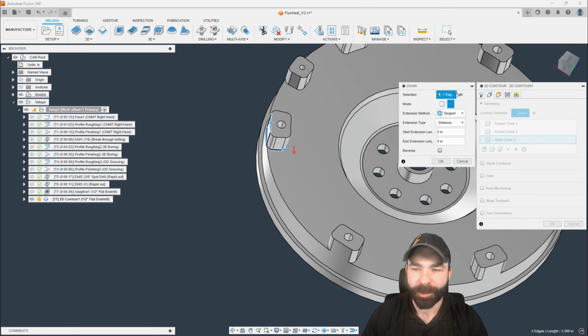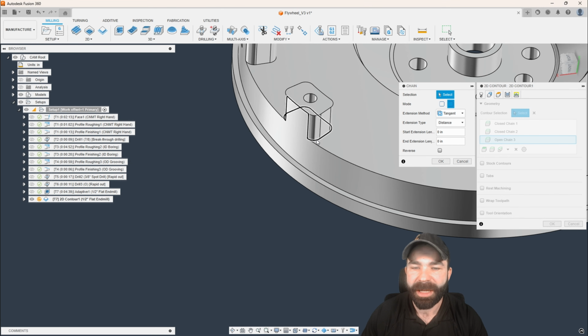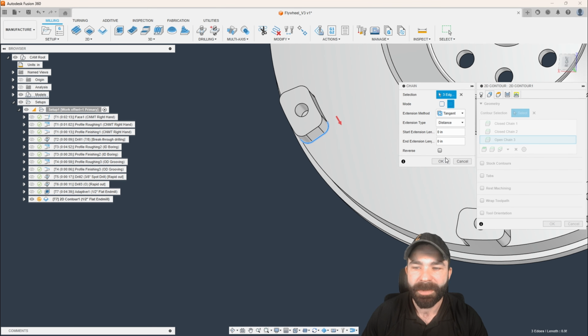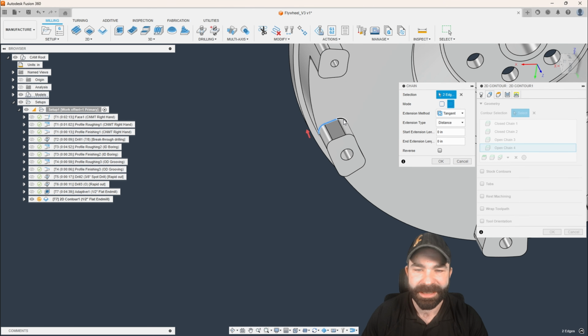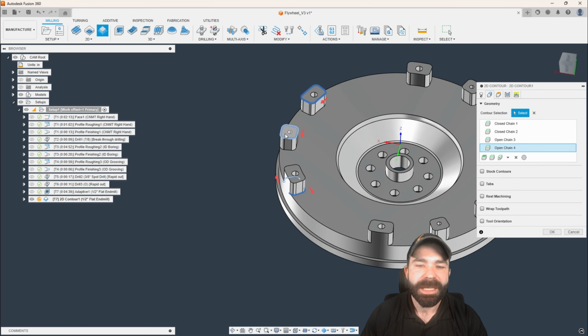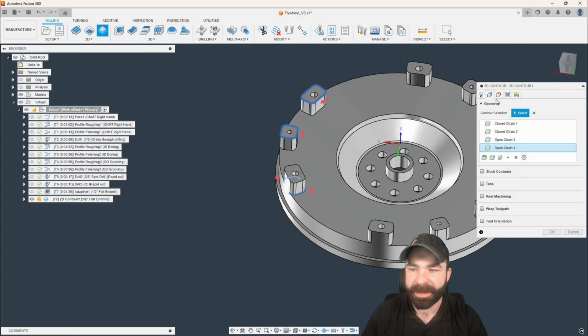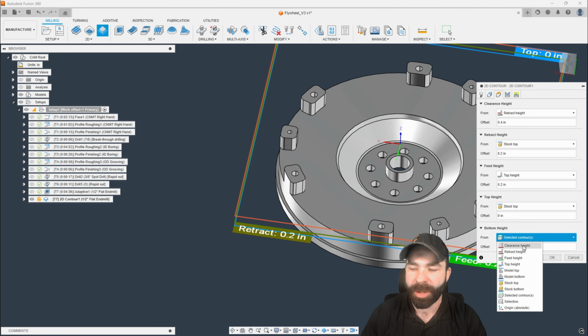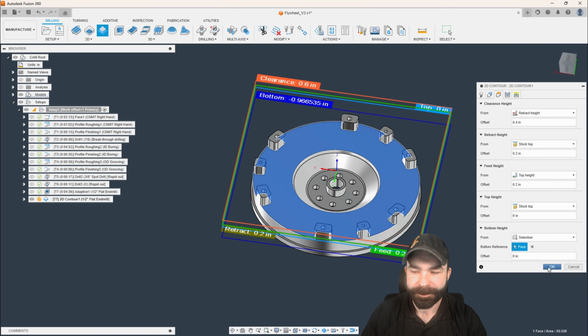Now, if I wanted to, based on machining time and knowing what's already machined, I could reduce this even further and say I only want to machine this little area here, and then the same thing on the other side. But you're going to see that I'm going to start to cause a lot of selection on my part file. So we're going to do this a couple of different ways, but see how I have my upper ones done and then I have the lower one here. It's not going to make a big difference because we are going to set them all to a selected face, and that's the bottom of the pocket here.